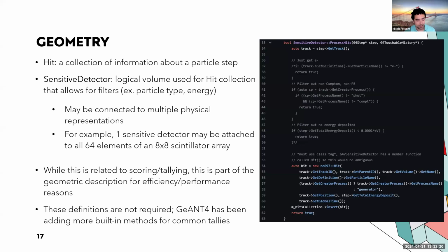And it's fast. You can use filters. I can say, I only want these particles. I only want these energies, et cetera, et cetera. Things going in this direction and all that. And so this is more detailed. It takes more setup, more boilerplate, but you get all of the information: the track ID, the parent ID, if it's a secondary, which volume it's in, what type of particle, what type of process created it, Compton, photoelectric, things like that. So this is how I've seen it when everyone's collecting tracks for real and they want all of the information, this is how you do it.